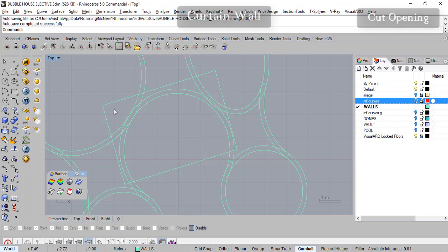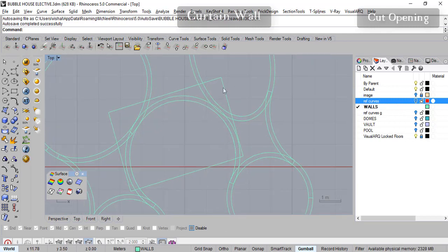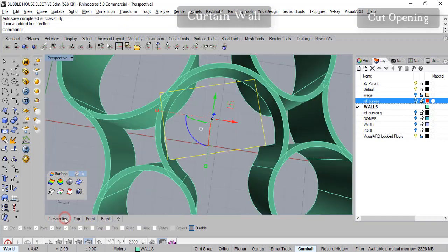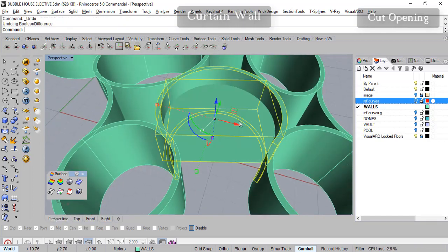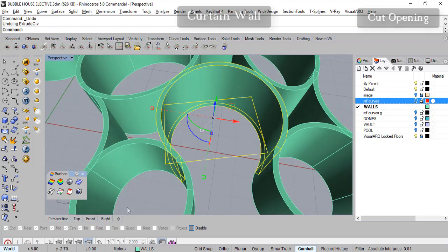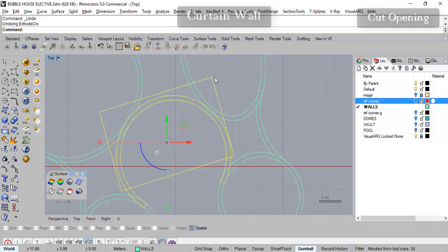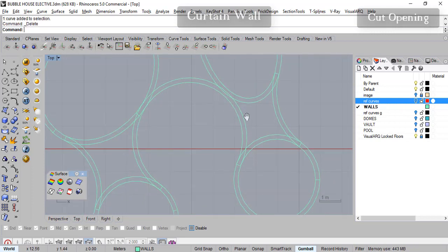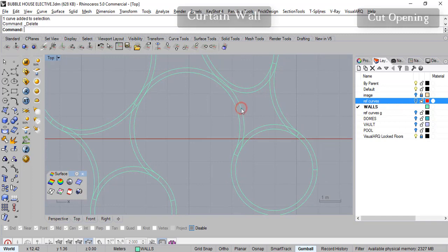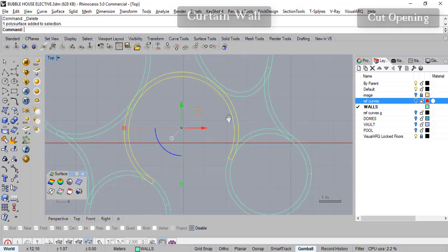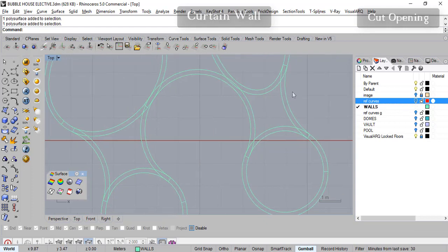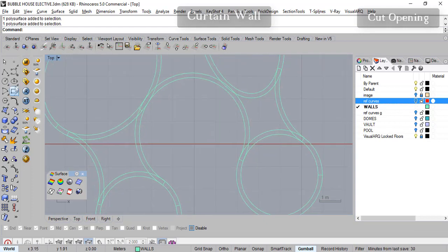So when I have this circle here, that circle will cut away all of these walls inside of it. So the square extrusion doesn't work for us. So we'll have to undo this. Control Z a couple of times. Come back to the top view and we'll delete this. So let's draw a cylinder instead, but for drawing the cylinder we can just take this circle. We don't want the walls, so we'll have to look at the reference curves, or we can draw a fresh curve.